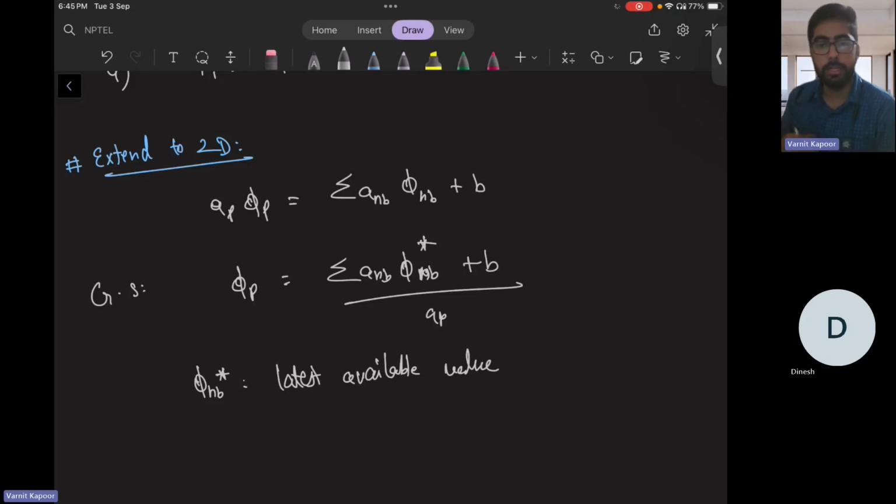Now in 2 dimensional, the Gauss Seidel is pretty slow, because information travels cell by cell, from one cell to another, then to another. And you see the boundary conditions are felt as per the iterations, so multiple iterations happen.